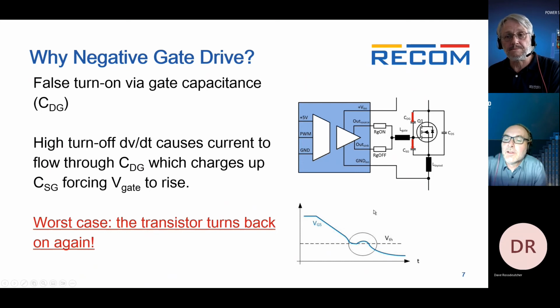Okay. So there are some more challenges, I think, especially also in the layout, and what you have to really take care for, because of the high switching frequency you have in the system. If you're switching like 1,000 amps per microsecond, which is entirely possible with these kind of power levels, even a 5 nanohenry inductance will generate 5 volts across it. And 5 nanohenries is a 5 millimeter length of PCB track. That's how sensitive the layout is.